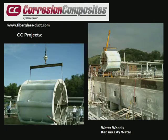Go on to the next one. Here you're looking at another unusual project. This is the city of Kansas City. And they had first designed these wheels, we call them water wheels. And what they do is, if you look down in the lower right, you'll see some big wooden paddles. These paddles mix the flocculant into the water coming into the plant. The flocculant is mixed with the water to drop out all the particulate before the water goes to the clarifiers. It's a common practice in water plants.